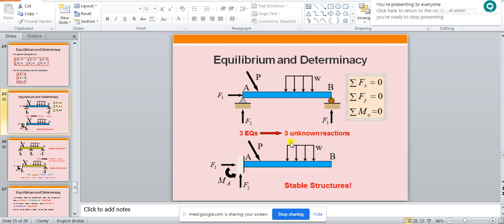Now coming to the next problem. The next one is a very simple case, a cantilever beam. In this cantilever beam there is some UDL acting vertically, and then there is some kind of point load acting. This point load is acting here in an inclined direction. If it had been acting in the vertical direction, there would not be any horizontal reaction at this support; only a vertical reaction would be obtained at this support.